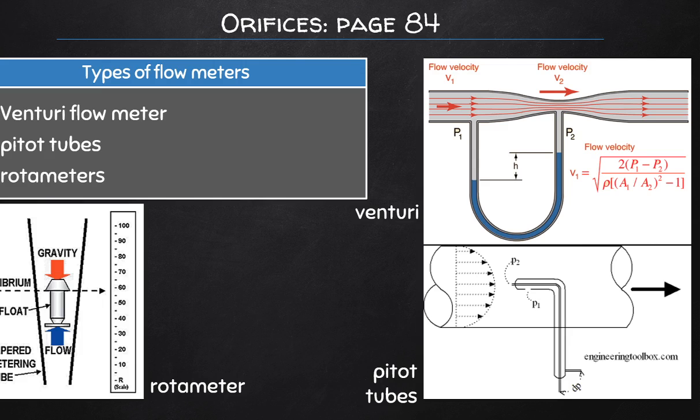Okay, how do we typically measure flow? Now this is another question. It all depends on the type of fluid, the geometry of pipe, as well as the rate of fluid being targeted, and also operating conditions, pressures, temperatures, corrosivity, hygiene, etc. Now there are many ways to measure flow, and it is up to you to orient yourself with the various types of instruments. Now a flow meter can either measure mass or momentum, in other words velocity, or volumetric flow rates.